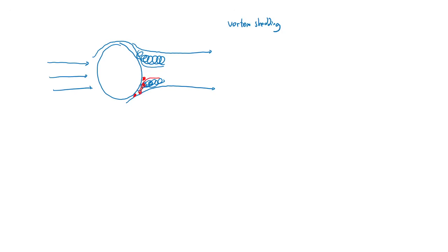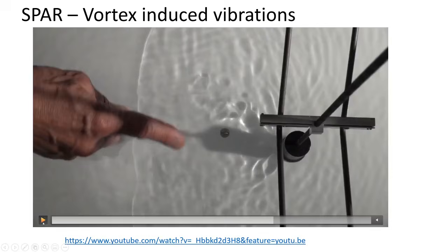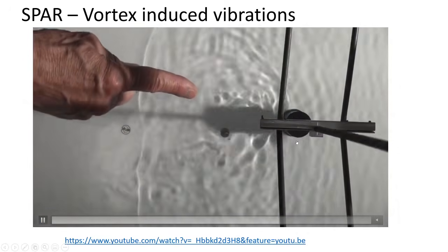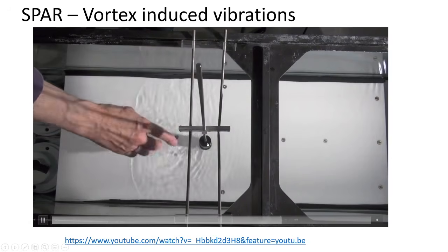So the fluid might follow correctly until here, or it might detach early. And it will oscillate: when this is closer to the center, this is going to be up, and then when this is closer to the center, this is going to be down. Okay, so you see this generates the following movement. It generates some forces that cause the cylinder to start to move and oscillate.